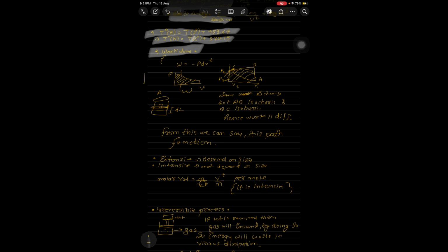So the gas is compressed this much. This is the length and this is the cross-sectional area. Area into length gives you the change in the volume. So we can write work as force into displacement, or we can use L also, and we can also write it as pressure into area into dl. This gives you the volume, so we can also write it as pressure into the change in volume.